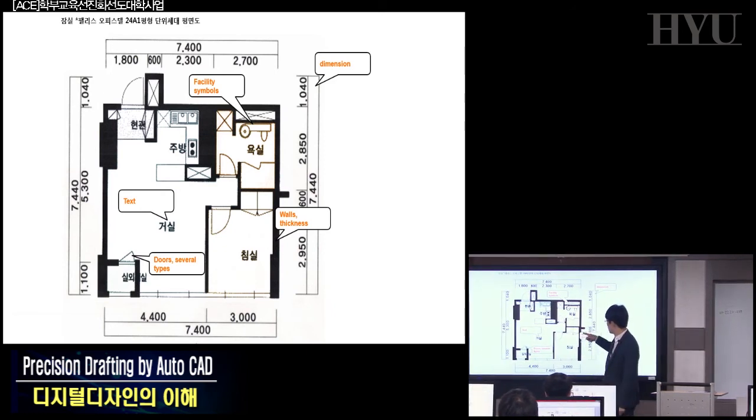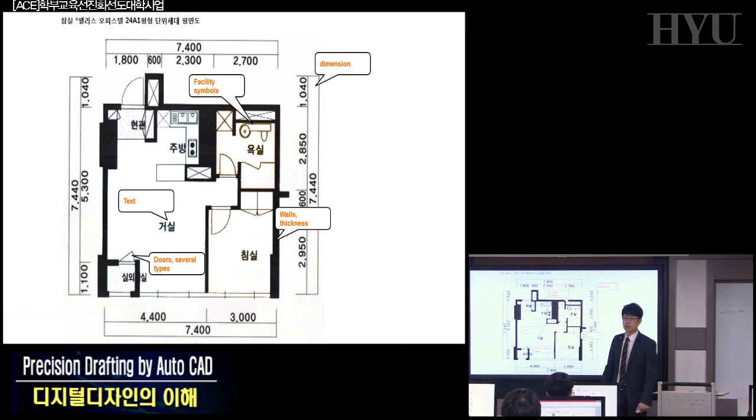Firstly, you can draw exterior and interior walls, considering thickness, okay? I told you 300 for exterior wall, and usually 200 millimeter wall thickness for generic concrete walls.